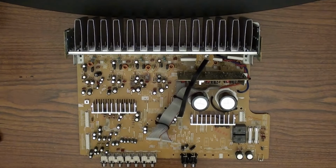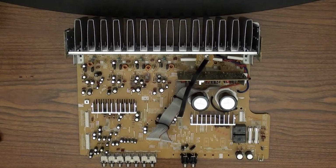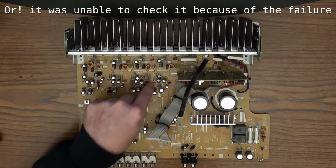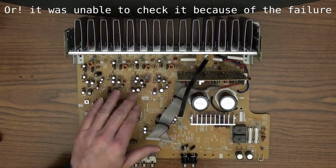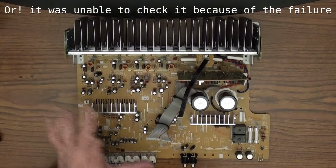So, the error message that displayed on the front, I'll show you right here what it displayed. It displayed everything. The NG is supposed to stand for no good, and then it displayed the L, C, R, SL, BL, BR, which is all the channels except for the SR, which is the surround right channel. So in other words, it says the surround right channel is supposed to be good. That's the way I understand the service manual. Well, this is the surround right channel, the one that has the burnt up parts on it. So this is the problem child, then all the rest of them are no good. So it seems a little flaky there to me.